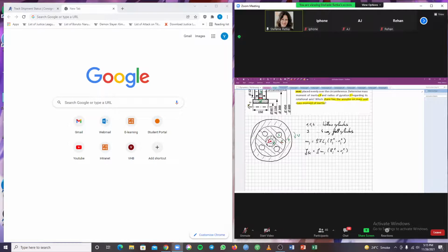Now, as you learned in statics, we can build a table and simply fill in the relevant information for every subsystem, and then we can sum over the subsystems to obtain the absolute value. So we need the number of our subsystem, then we need the radii, outer and inner. I'd recommend stating them in meters right away, then we do not have to worry about the dimensions.